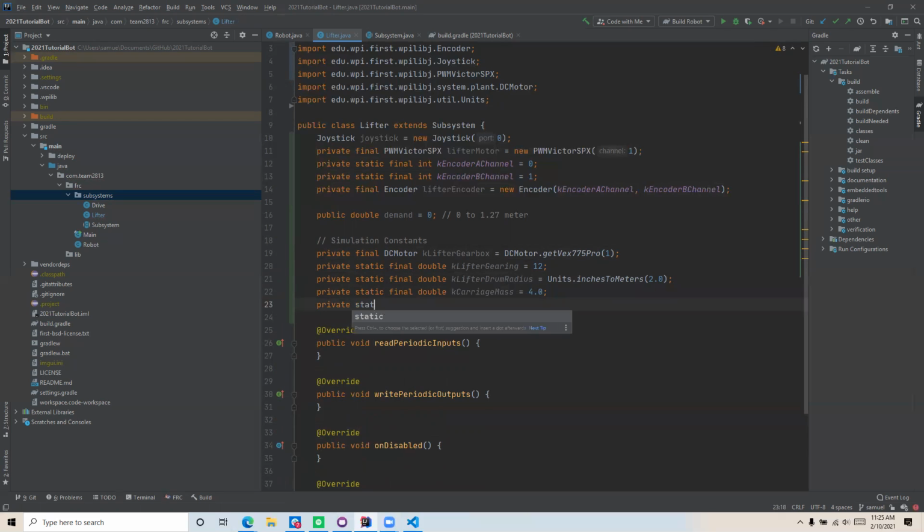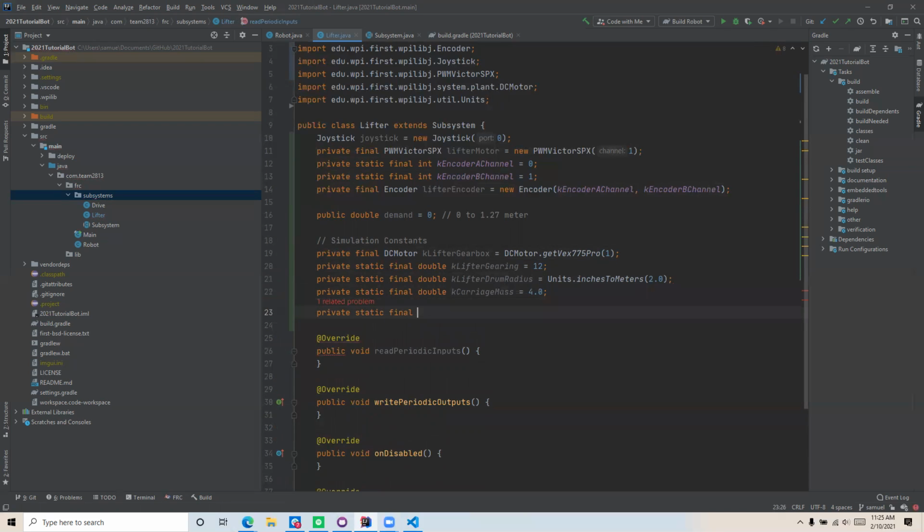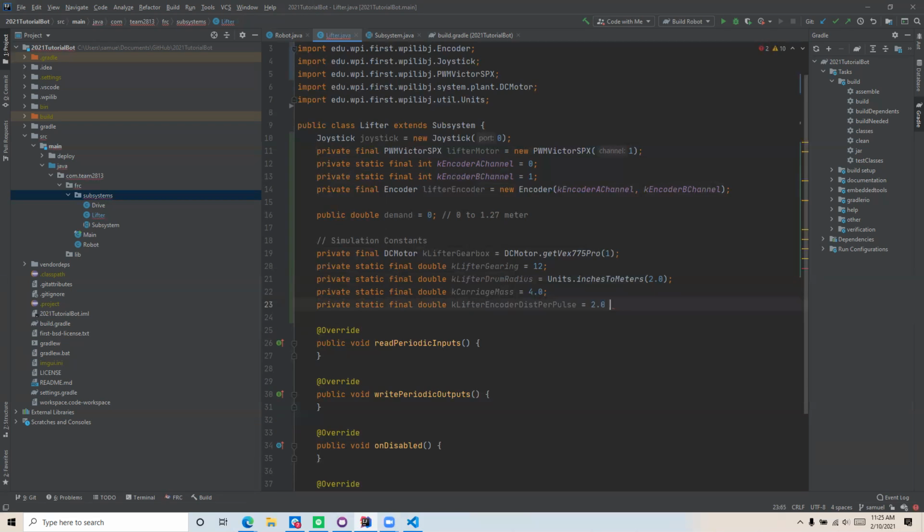And then, so the parameters have already been measured. Yes, that's correct. So we're basically just putting in stuff that is already known to us. Okay, so physical measurements of the robot. Okay, and right now this is just some fancy math for encoder distance per pulse. Basically, an encoder will, if the encoder reads 4096, it reads an inch or something like that. Right. And again, this is given stuff. Depending on the hardware you purchase and install, these numbers will be different, but they're all known numbers. Okay.